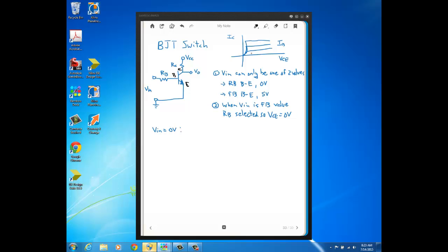Now what you'll see is that when the BJT is used as a switch, we're either operating near the horizontal axis where both the base current and collector current are ideally zero, or in actuality very small, and that's called the cutoff region, or the transistor is being operated along the vertical where we have a small VCE, ideally zero, and some amount of collector current. And you'll also see that in this region you do have current gain, but it's not the optimum current gain.